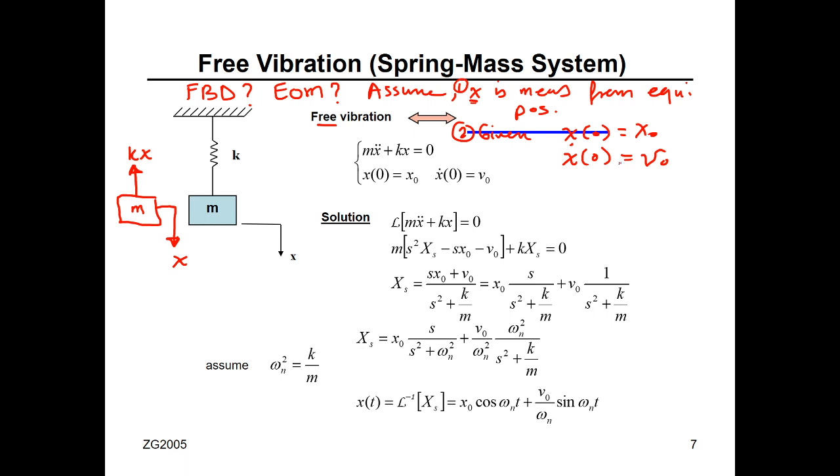Okay, that's it guys. By the way, in most of the problems, in fact in all problems that you see in the field, x is measured around the equilibrium position. Like your car, for example, now on the street, it's on static equilibrium position, the suspension system too. Your engine, your pump in the field, always on static equilibrium position. Any vibration or displacement is around that position. That's why we always assume in the problems that we are measuring from equilibrium position. So this is your free body diagram.